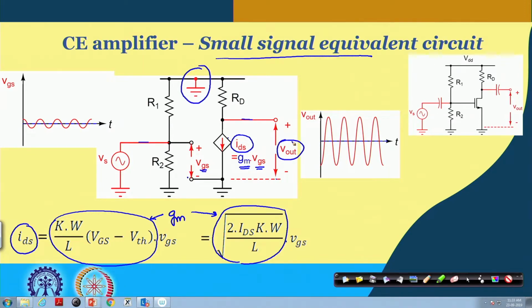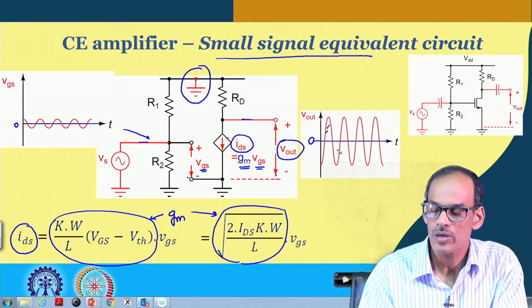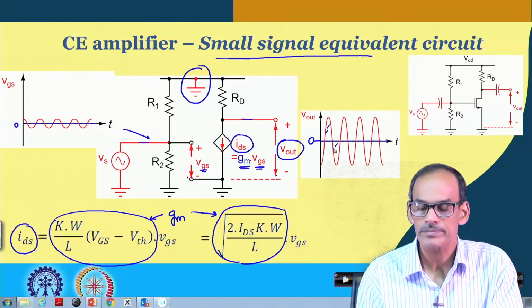small signal output. So, just to highlight that the signal here, it is not having any DC, it is having 0 here, and whatever you are observing at the output, that is also having DC equal to 0. So, at the output we do have only the signal part.